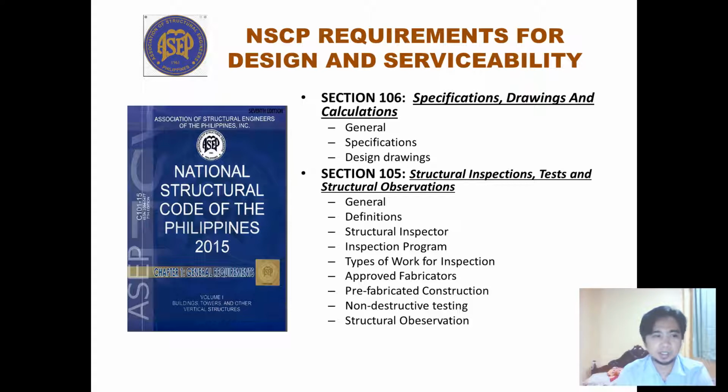Okay, so in implementing of government projects, there are a lot of checklists to follow in the implementation. Okay, so there are checklists for pouring of concrete, installation of rebars, and even design workability, or the workmanship, pertaining to the workmanship during and after construction. So that can be found in the RPMS checklist that is strictly to be followed.